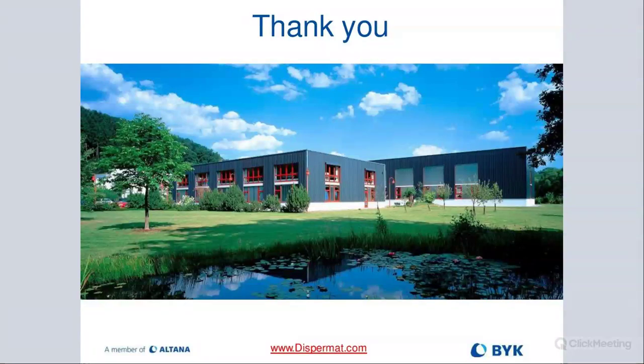But generally, what we want to do is match what we do in our lab, where we got the good results, and we want to keep the ratio the same. That is the most important thing, that the ratio stays the same. Not only the blade ratio, but also the container ratio stays in sync. The blade-to-container ratio is the same in manufacturing.